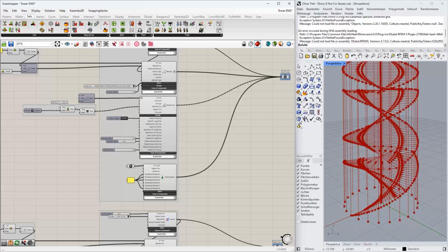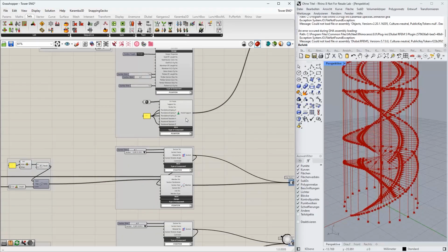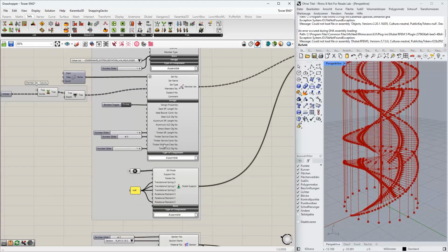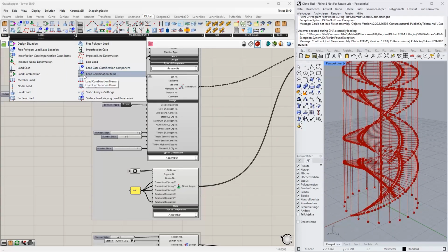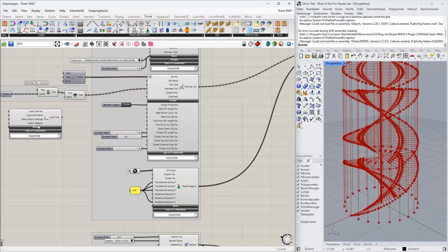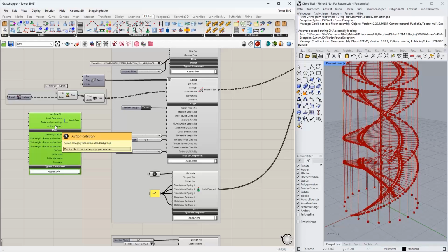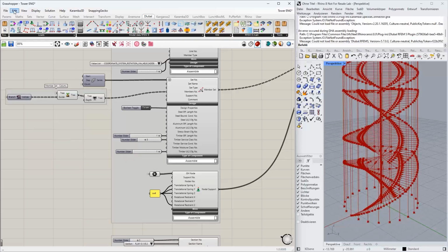Okay, that's what I wanted to show you now. What should be next? So yeah, and that's why we use templates at first. And what's else the benefit of using these templates? This also allows us to control or define loads very quickly, so we don't need to define load cases and load case combinations inside Grasshopper. You have the possibility to define it inside Grasshopper, but if you already defined this in your template in RFEM, you can just refer to this template and don't need to define these components by yourself.